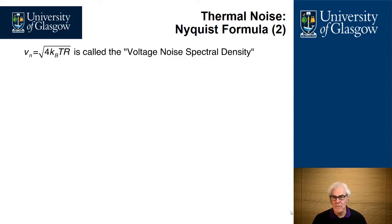We use the Nyquist formula. I know that many of you know about Nyquist as a sampling theorem, but Nyquist was a communications engineer and he did a lot of studies into theoretical communications. Here we have the calculation for noise voltage, and it's the square root of 4 times the Boltzmann constant times the temperature times the resistance.